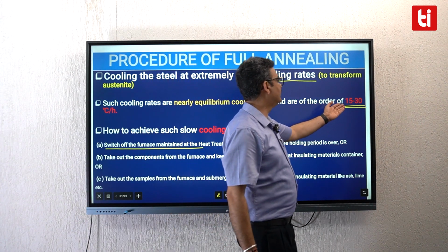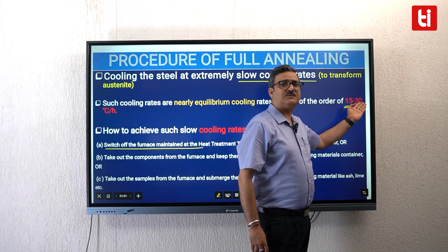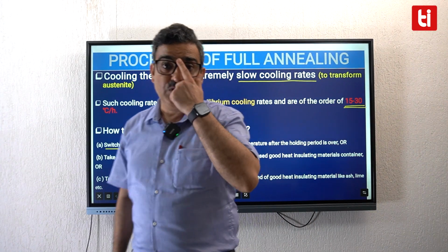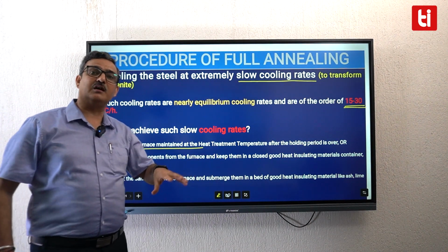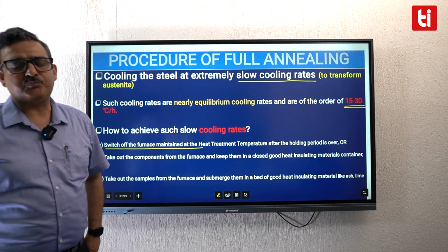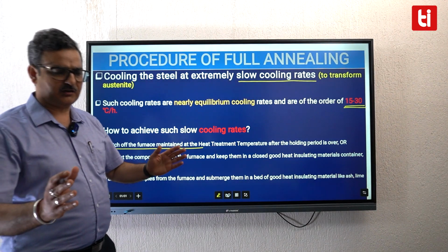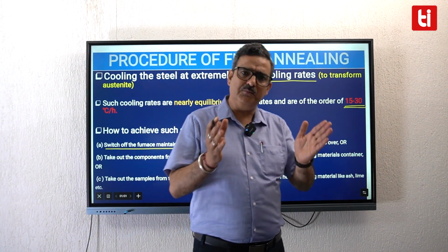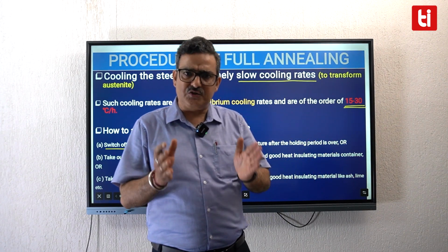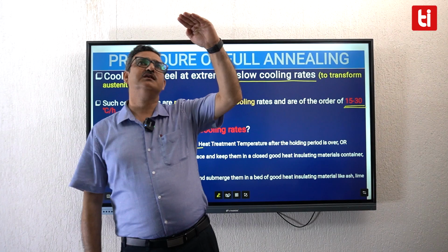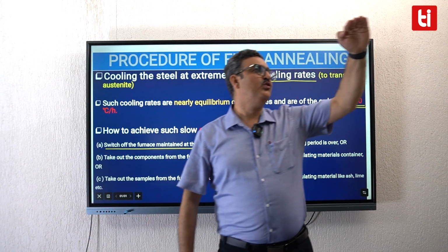बच्चों, अगर 800-900 डिग्री सेंटीग्रेड पर आपका स्टील स्पेसिमन पड़ा हुआ है और आप हदोहद 30 डिग्री सेंटीग्रेड पर आर से कूलिंग करोगे, फर्नेस में ही पीसेस को रखकर 30 घंटे लग जाएंगे यार एक बैच ऑफ प्रोडक्ट्स को प्रोसेस करने के लिए. सो दिस इज जनरली नॉट ए प्रैक्टिकल मेथड. तो आप क्या करते हो, कुछ अच्छे हीट इंसुलेटिंग मटीरियल जो कि कुछ स्टील्स हैं, इंसुलेटिंग स्टील्स, उनके कंटेनर्स बना लेते हो. तो व्हेन यू हीट द स्टील कंपोनेंट्स इन द फर्नेस, यू होल्ड देम.